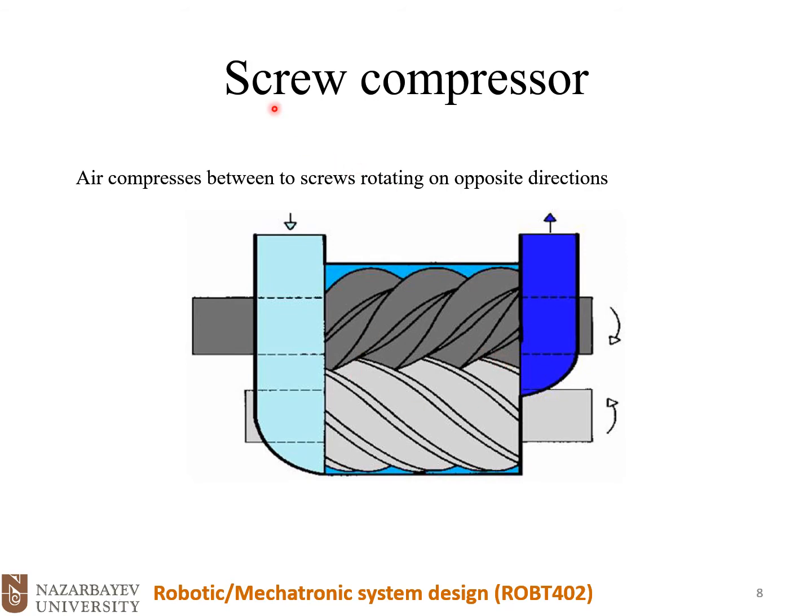Again, this type of compressor is a positive displacement compressor. Why? Because we are decreasing volume, very similar to the piston and cylinder, and by decreasing the volume we are increasing the pressure.